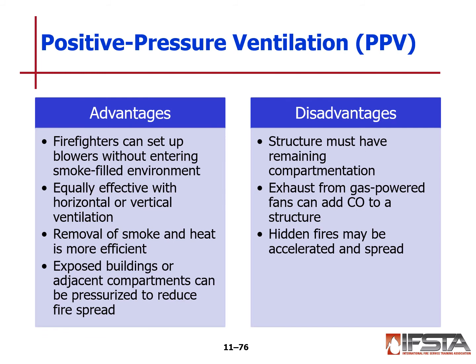So, advantages: firefighters can set up fans that are blowing in without entering smoke-filled environments. You're doing this from the outside. It's equally effective with horizontal or vertical ventilation. The removal of smoke and heat is more efficient, and the exposed buildings or adjacent compartments can be pressurized to reduce the spread of fire.